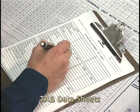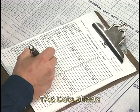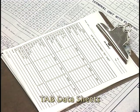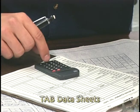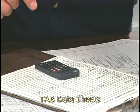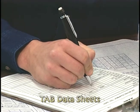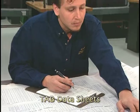After the initial review of the documents, the technician fills out the preliminary data sheets. It is essential that the TAB data sheets are filled out correctly and legibly. After going over the data sheets and the other materials, the technician determines the most effective balancing procedure for the system, as well as identifying any potential problems that may affect the balancing or future operation of the system.